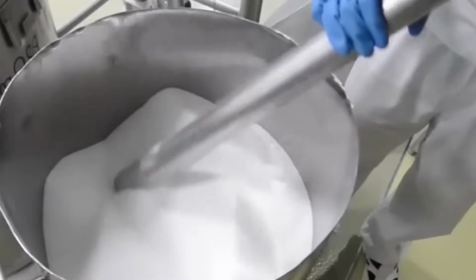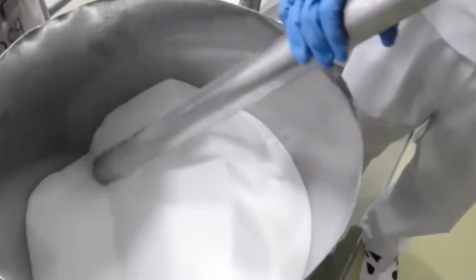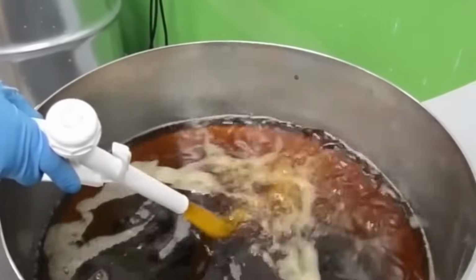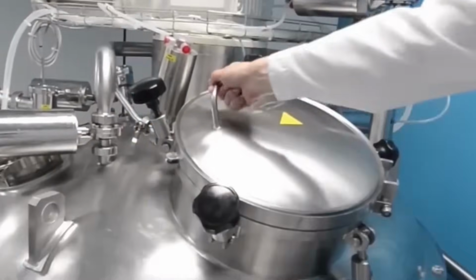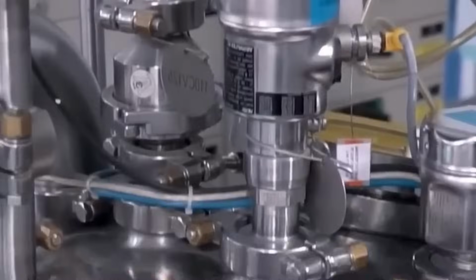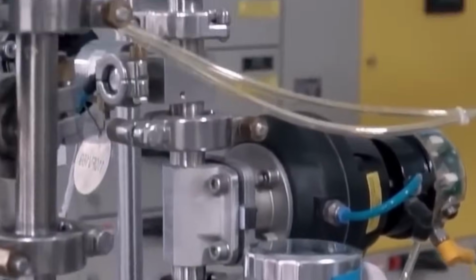A surfactant, usually sodium lauryl sulfate, is added last due to its foaming and emulsifying properties. It is introduced in liquid or paste form through heated lines maintained at 30 to 35 degrees Celsius to reduce viscosity. SLS is blended gently to avoid excessive aeration. The target inclusion level ranges between 1.0 to 2.0% depending on the formulation.